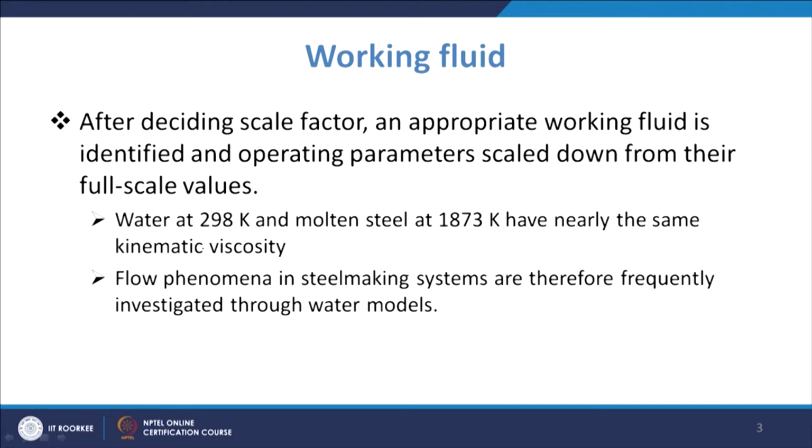It has been found that water at 298 K, about 25 degrees Celsius, your normal room temperature, and molten steel at 1873 Kelvin have nearly similar kinematic viscosity, that is mu by rho, and that helps ensure that you have a similar flow regime established in both the model as well as the actual tundish.